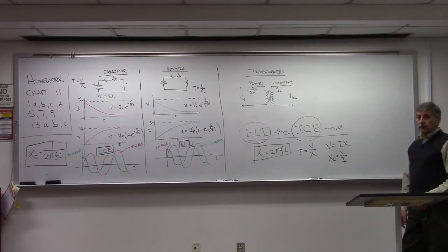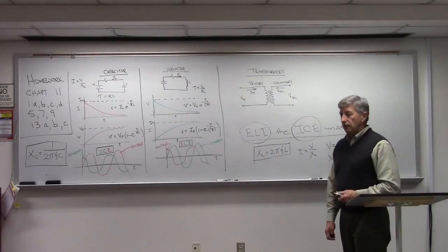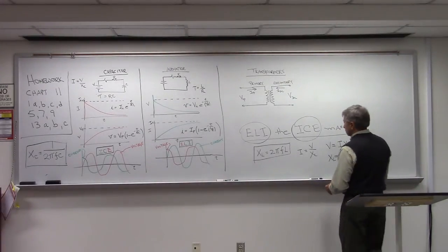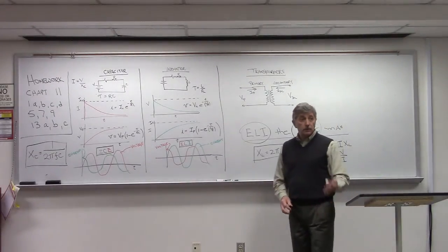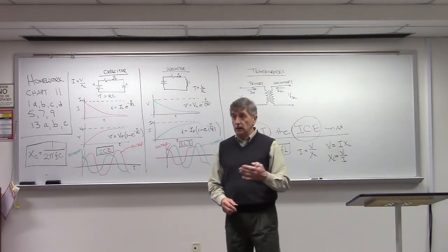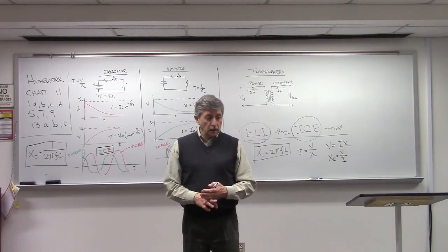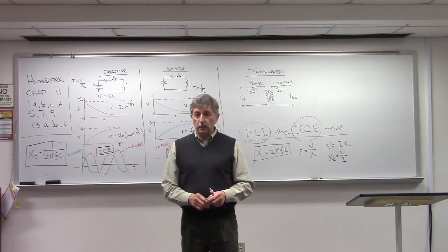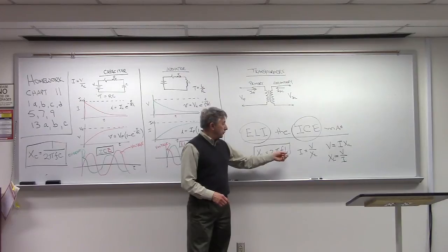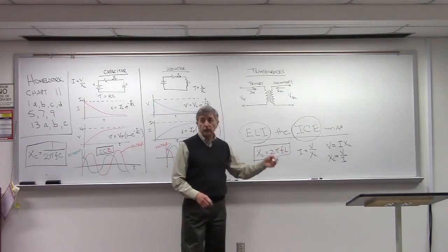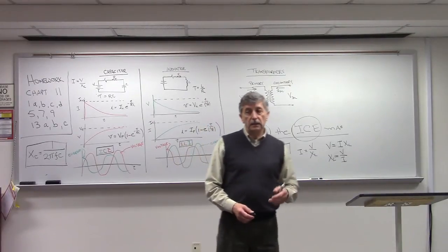You just replace R in Ohm's law with XL. So just remember, if you have a fixed inductor, and usually they are fixed, you can get variable inductors, they're not real common. If you have a certain value of inductance, and you change the frequency, then the inductive reactance changes.